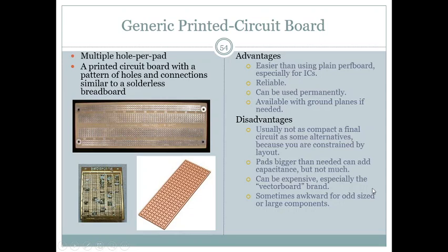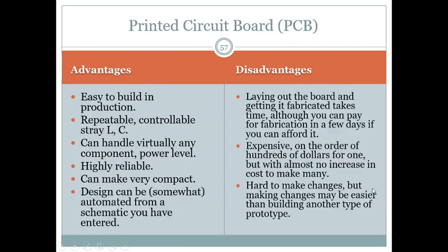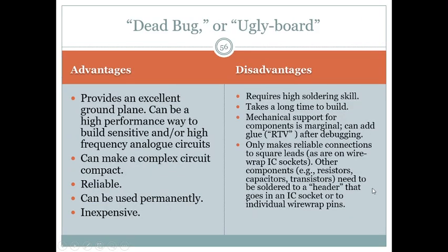Now you will be using this as well. In the evolution, first you will design it, you will test piece by piece, and then you will assemble the whole circuit on a breadboard and test it. Then you will be assembling it on a strip board or a dot board and test it, solder it. Then you will be designing a PCB, that is this one. The final would be a PCB, and thereafter that will be for assessment.